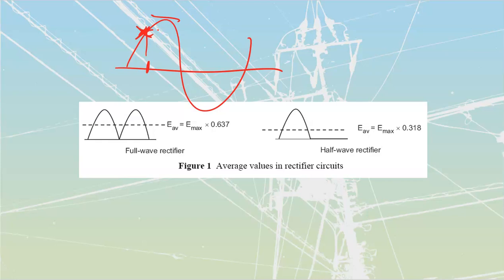We've also got our RMS, which is our root mean squared. What was the purpose of RMS? The purpose of RMS was going to give us the cross compatibility, right? We wanted to have a value of voltage that we could say, hey, this is my RMS value, this is my DC value for flatline DC. Remember we said we wanted a voltage that, if I had a flatline DC, would give me a certain amount of power and that I would be able to see the same amount of power from an RMS value. So it was an easy conversion. It's our most common one that we are going to use.